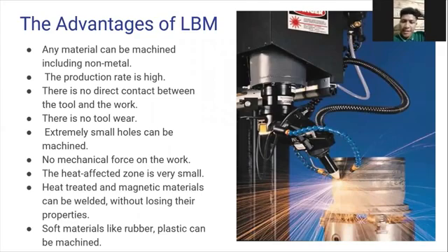And then the advantages of LBM. First, any material can be machined, including non-metals. The second is that the production rate is high. The third is there is no direct contact between the tool and the work. And the fourth is there is no tool wear.